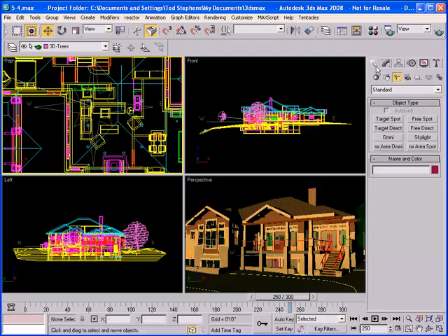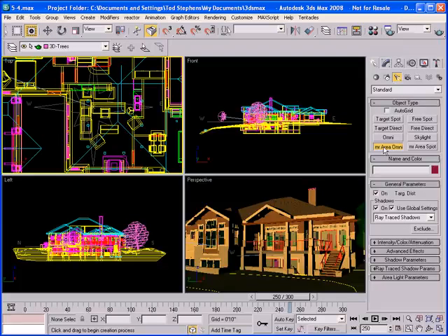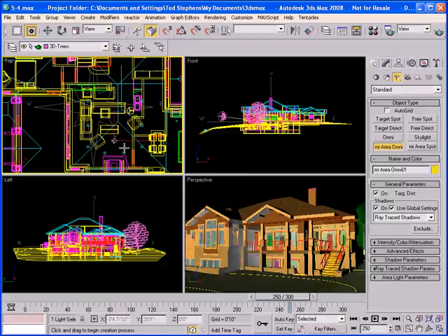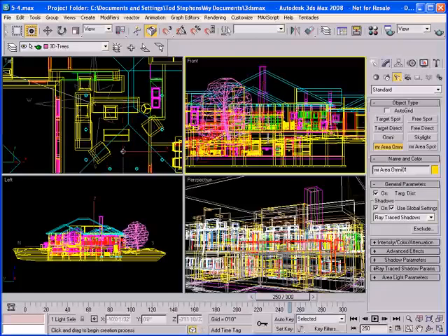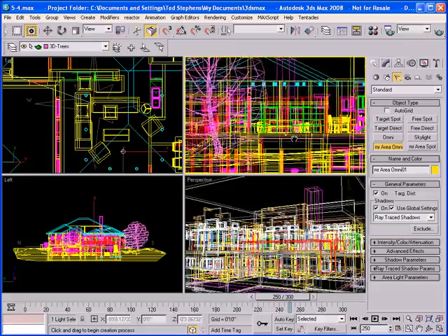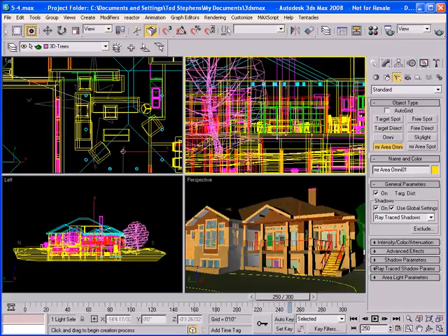Then I'll be able to move the light. So now I'm going into my lights again over here in my Create panel, the MR Area Omni, selecting that particular type of light. And then in that room, in the top view, the easiest place to put a light is in your top view. It's going to be a little tough to see, but in my front view, I'm going to zoom in. The light right now is sitting right on the floor. And you just kind of get used to seeing through all the different objects and trying to find stuff.